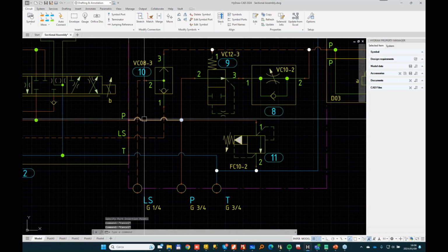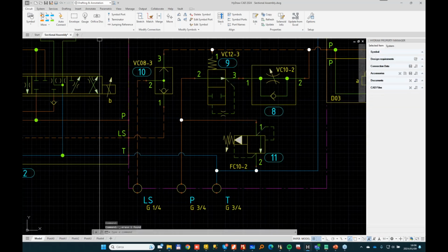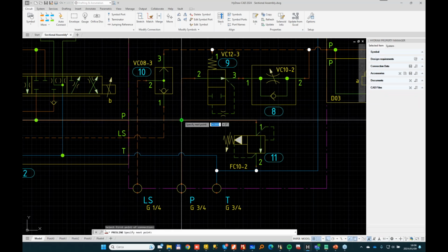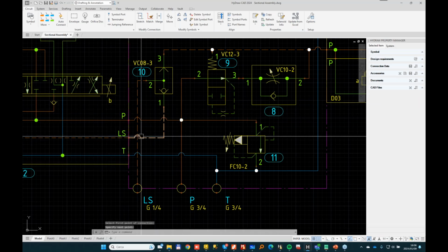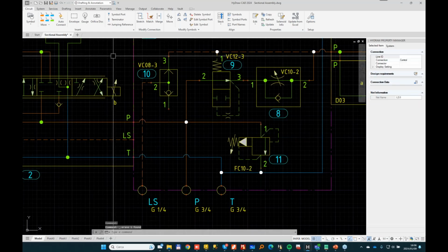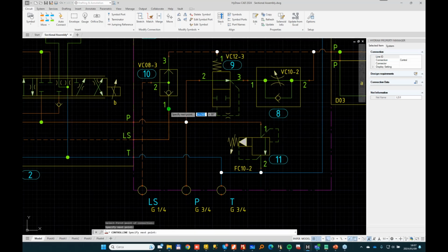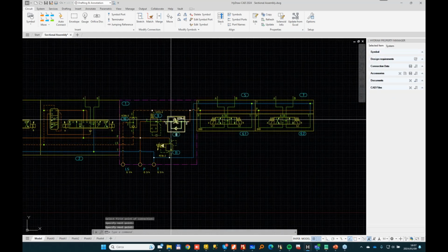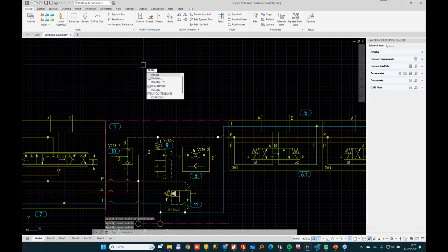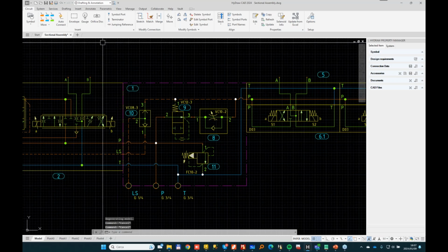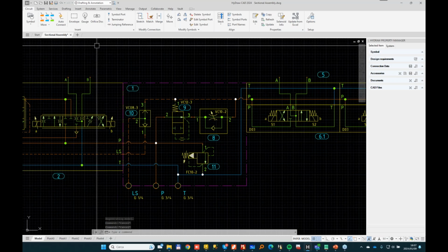So of course, now that I made this, it will be possible to make connection lines. As you see, there is the green dot showing the connection line. Similarly, I will be able to do it. You should not need to do the connection line again because they are there. Sometimes it's needed to regenerate the drawing. So that's an AutoCAD command, type regen, and it will regenerate the connections. So, two commands before going to MDTools.